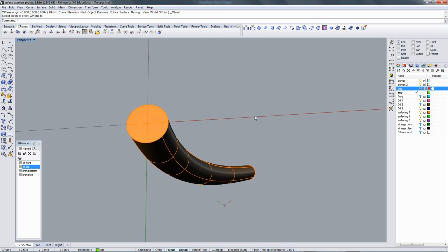You would want to have some kind of reference geometry to snap to, which we did here, and it would just be a rotate C-plane command, set to 0 for your center of rotation, the Z-axis, so you're looking right down on it, a shift key for your where it is now reference point, and an end snap for the where you want it to end up reference.